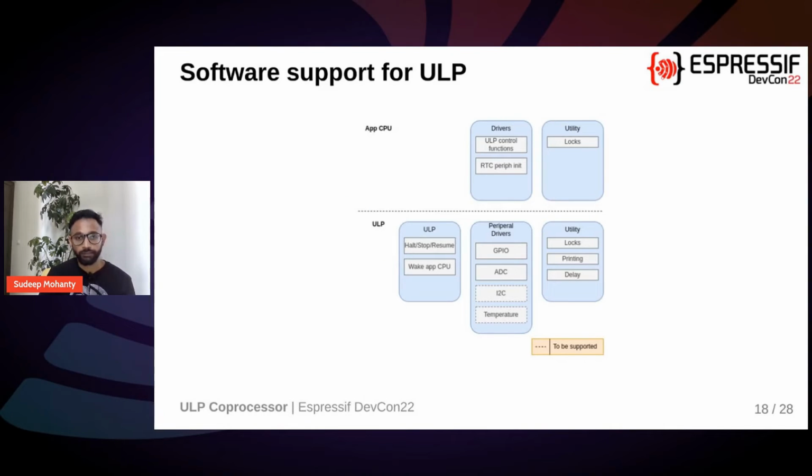Let's go a bit into the highlights of the software stack that is supported for ULP. There's a ULP driver that comes along with ESP-IDF. This driver provides access for the main CPU to control the ULP core, and also provides access for the ULP core to different peripherals that the ULP has access to, for example, the GPIOs, ADC, I2C, and temperature sensor. Some of these drivers are not yet built, and they are in the plans.